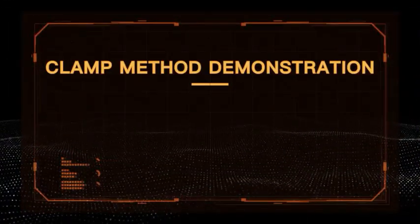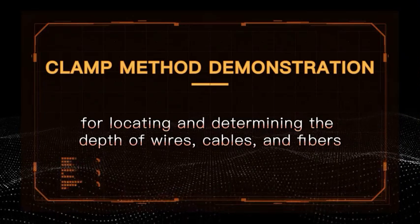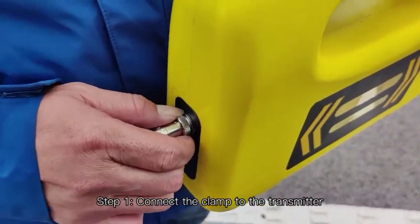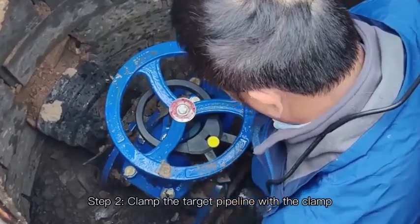Clamp method demonstration. For locating and determining the depth of wires, cables, and fibers. Instrument operation steps. Step 1. Connect the clamp to the transmitter. Step 2. Clamp the target pipeline with the clamp.